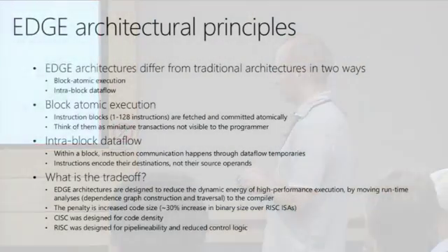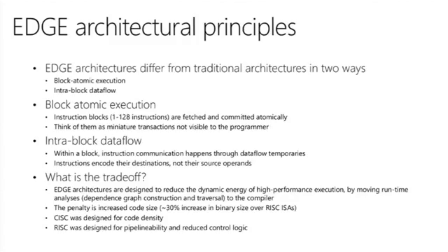You know, so in some sense, both of those were storage-efficient architectures. One was instruction encoding and one was control logic. What we've actually done is taken an opposite approach, which is to say, we're actually going to increase the code size and bloat the binaries by 30%, and in some cases as much as 50%. In deeply, deeply embedded devices where you still have tiny amounts of memory, this can certainly be a problem. But in the phone and wearable space, we think it's actually an appropriate trade-off.